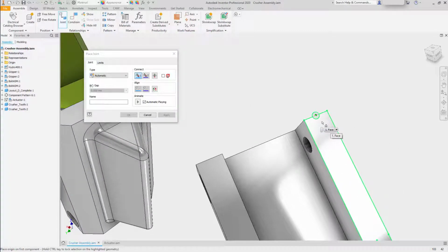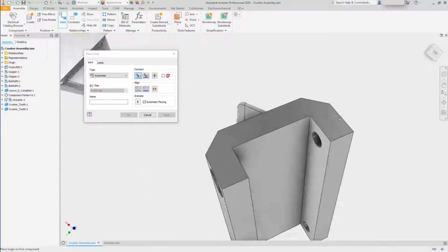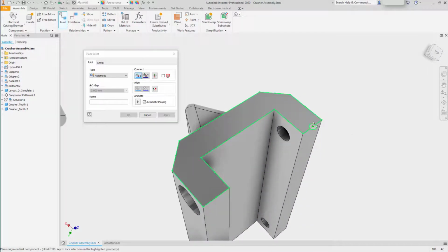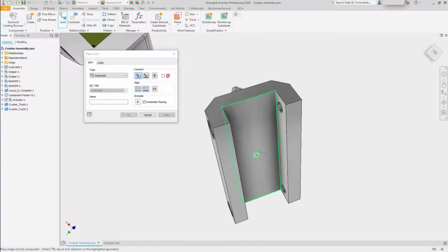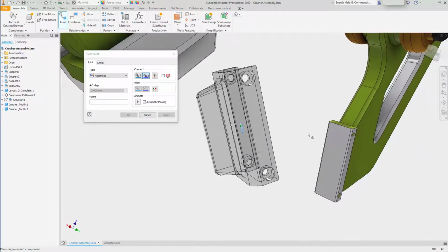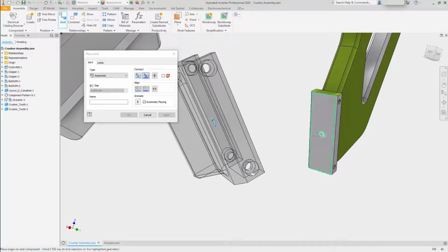any given point, such as the middle of this edge, can have 3 different orientations. So right now, the normal of this orientation is perpendicular to this face, or aligned to this edge, or perpendicular to this face. So selecting the same point can give you different results. I'll select the centroid of this face, and then find the centroid of the face on the claw.